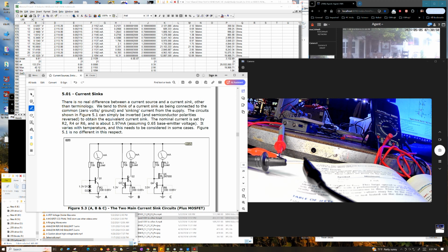But when this voltage gets high enough, and you understand when you first turn the circuit on, this transistor Q2 is off, but current will actually flow through this transistor's diode from this 10K resistor and through this resistor and start causing the voltage to increase as the power supply comes on.